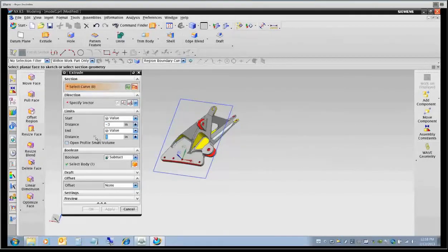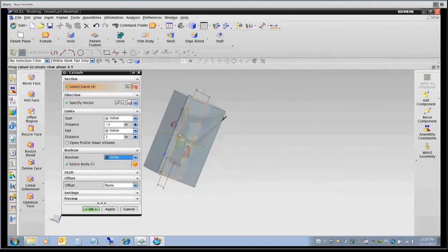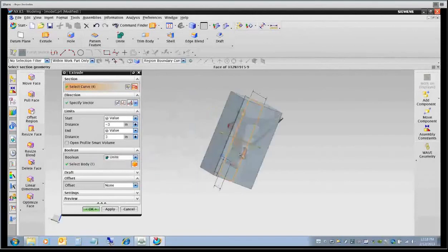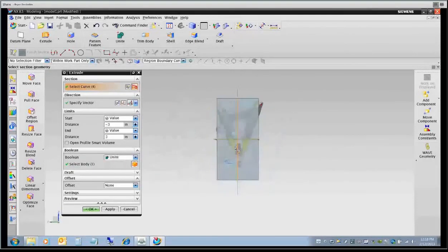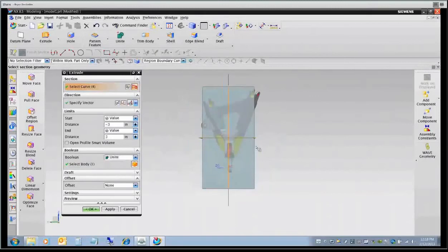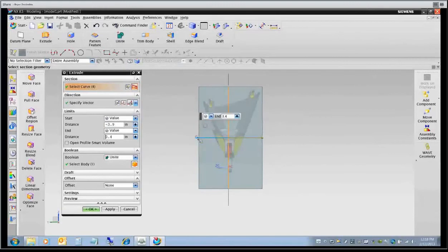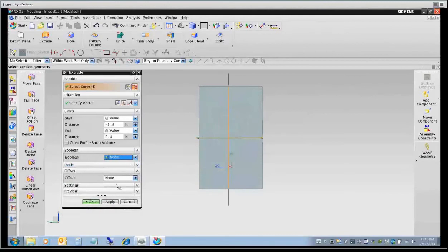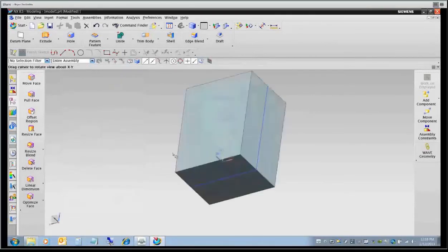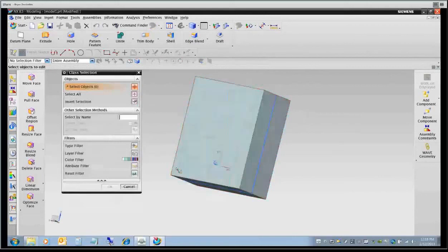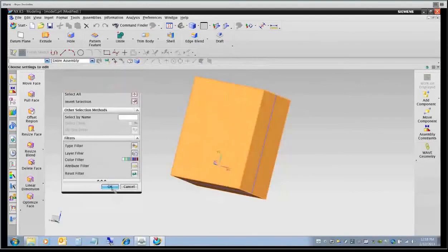And so we're going to use that in the center, and we'll work on both sides of this. Right? And so we'll go in here and tell it that this is the geometry, which is this particular guy here. So there he is. I'll just bring him out here a little bit for you. You could snap him to the side, take a look at that, and you can grab a hold of these as handles. You can drag it. You can enter a value, right? You could maybe create dimensions to the side, etc. So there we can take a look at that and then say we're just going to create this as a stock, or blank piece of material, if you would, for that.